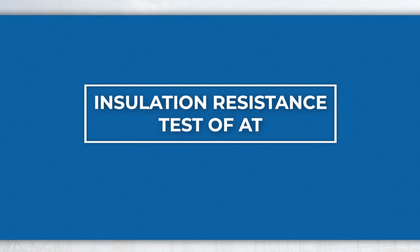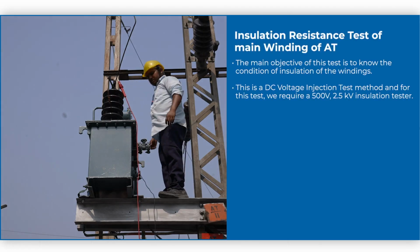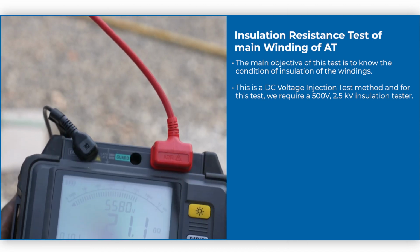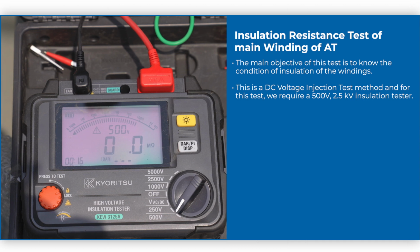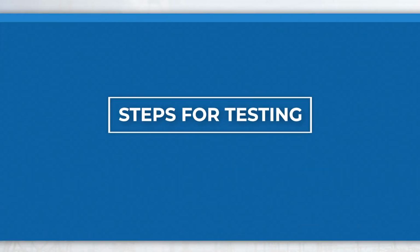Insulation resistance test of AT. The main objective of this test is to know the condition of the insulation of windings of AT. This is a DC voltage injection test method, and for this test we require a 500 volt and 2.5 kV insulation tester. Steps for testing.